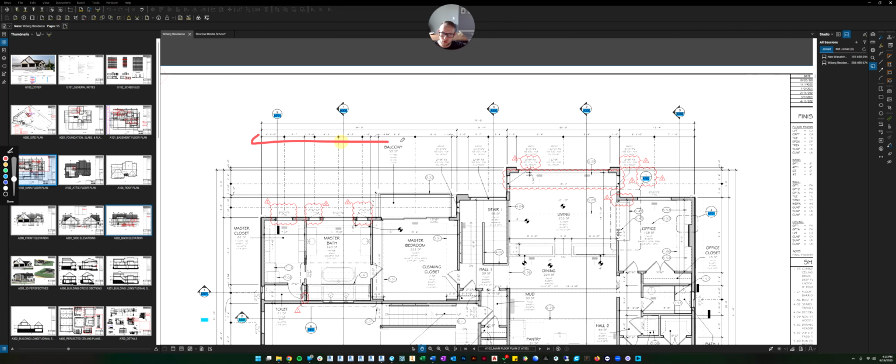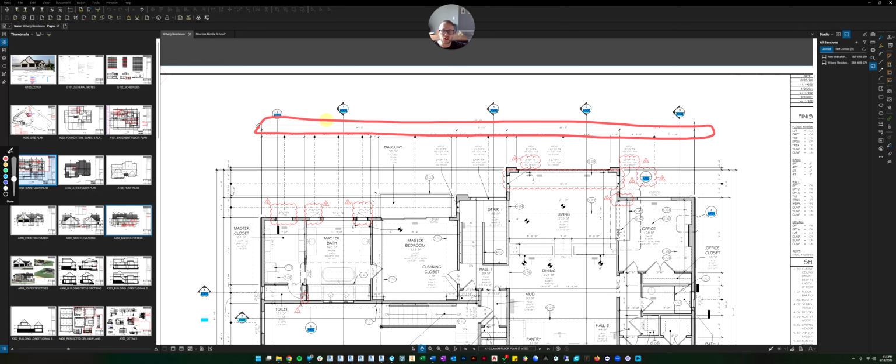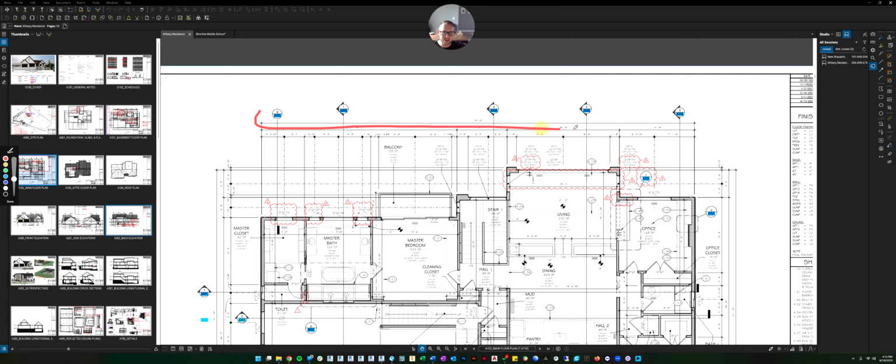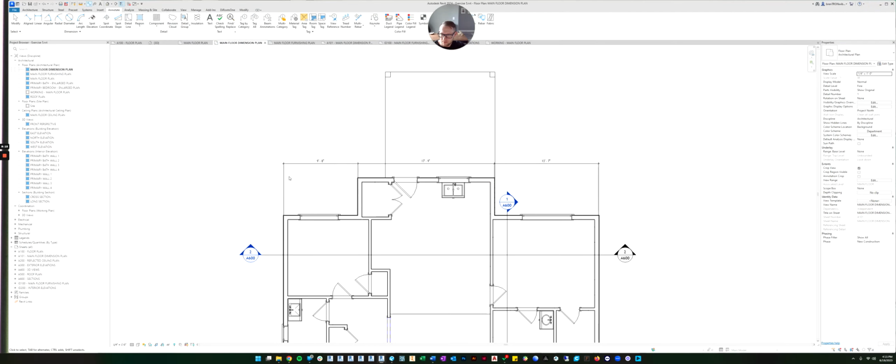So the first row, we're going to get everything. Openings and jogs in the wall. Then the second line is any jogs in the wall. That's the dimensions we just drew in our Revit model. And then the last one is the overall width of the building. So let's go back into Revit and let's do that for the back wall.